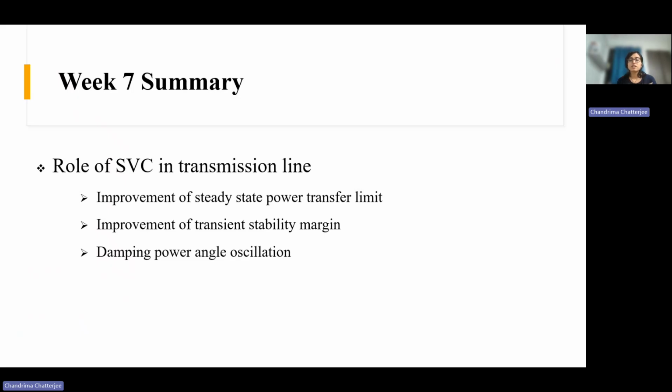During light load condition there may be severe over voltage, and during rated or near rated load we may face severe under voltage. That is detrimental for the power system and the equipment. To maintain the voltage at a safe value, we need reactive power compensation, and that's when the role of the SVC comes. That is the main role, to maintain the voltage.